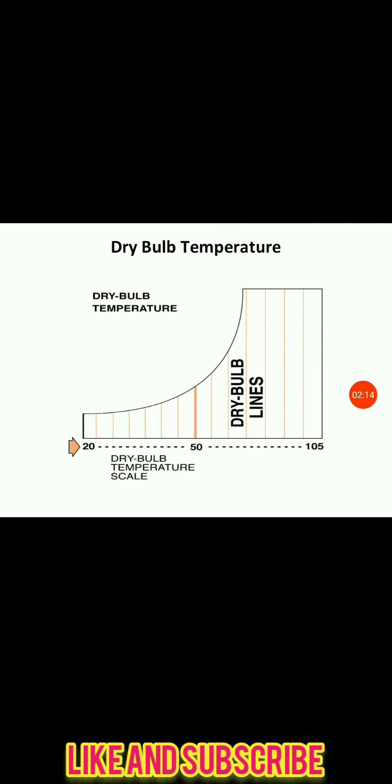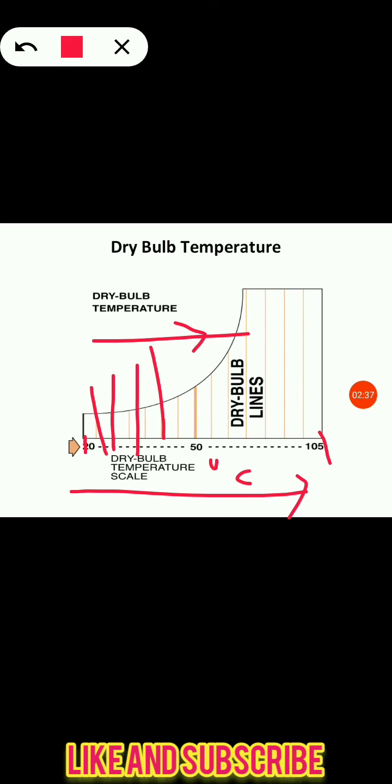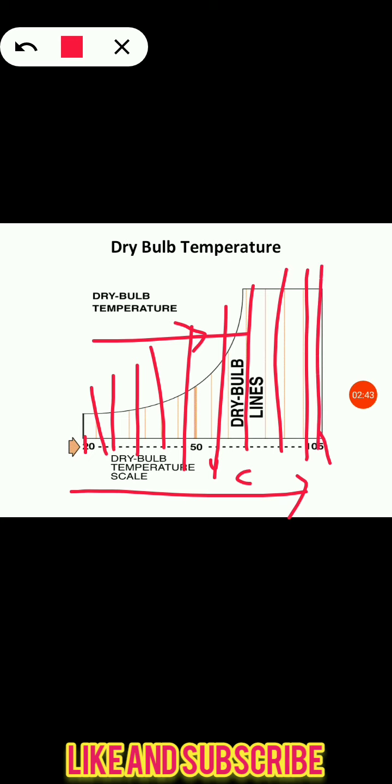First, we can see the dry bulb temperature. This horizontal line indicates the dry bulb temperature line. Here you can see it starts from 20 degrees Celsius and ends at 105 degrees Celsius. As we move from left to right, the dry bulb temperature goes on increasing. Dry bulb temperature lines can be drawn as a vertical line up to this end line, which is shown as the specific humidity line.